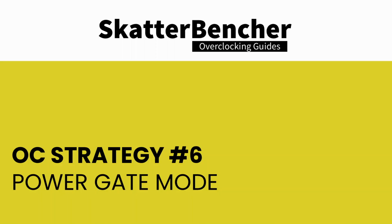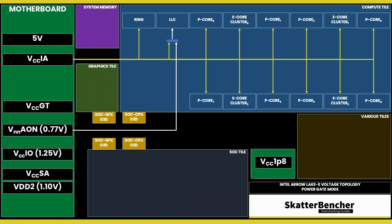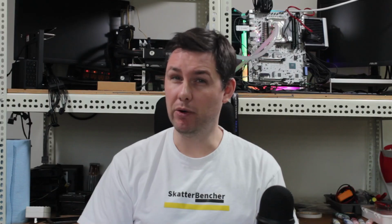In the final overclocking strategy, I have a look at PG mode or power gate mode to see if it can help improve our overclocked performance. In power gate mode, all the DLVRs tied to the VCC-IA voltage rail are bypassed and the connected IP blocks are powered directly by the VCC-IA voltage rail. Power gate mode is basically how the VCC-IA voltage rail worked on previous generation Raptor Lake.